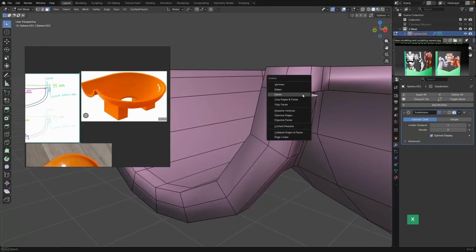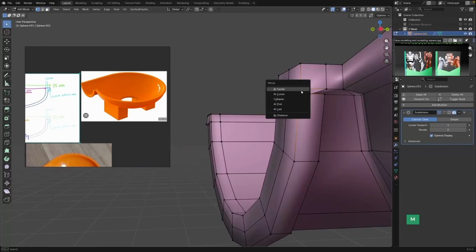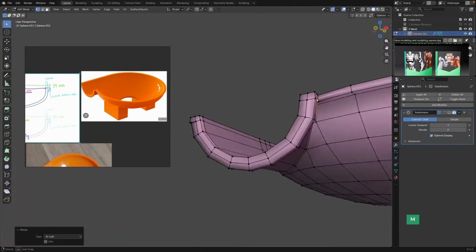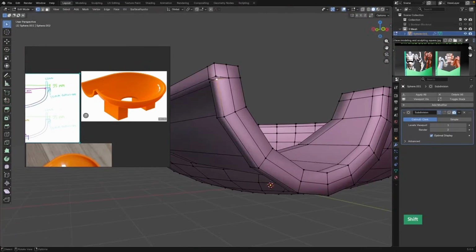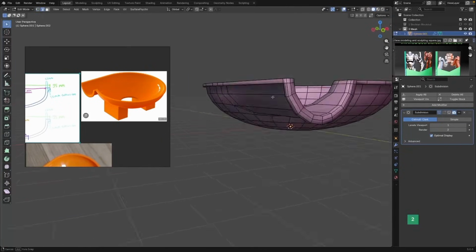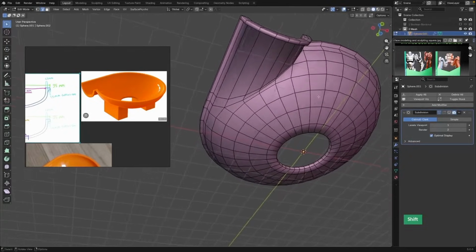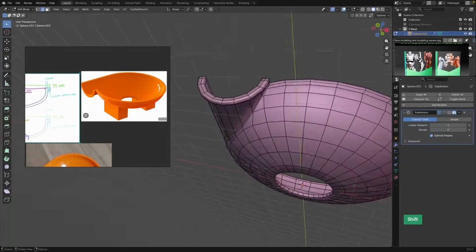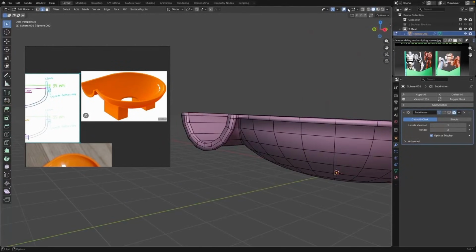So now we have a nice extrusion, and we just need to delete that face and merge these vertices. M and then merge it last. And that looks good. And let's merge it on the other side. I should have deleted the inner face there, but I forgot. And you will see that it causes me some trouble later. So it's good that it happened. It's always good when there's a little mistake. Then I can tell you what to do when that happens.